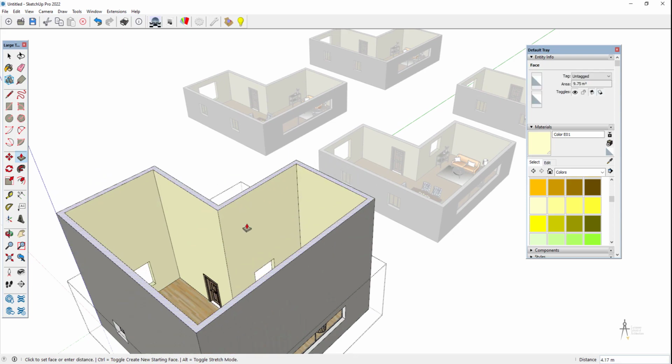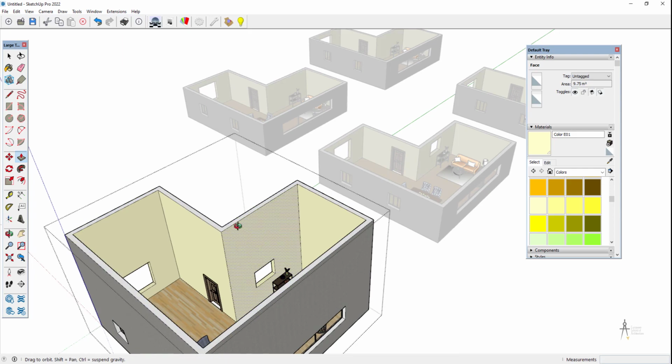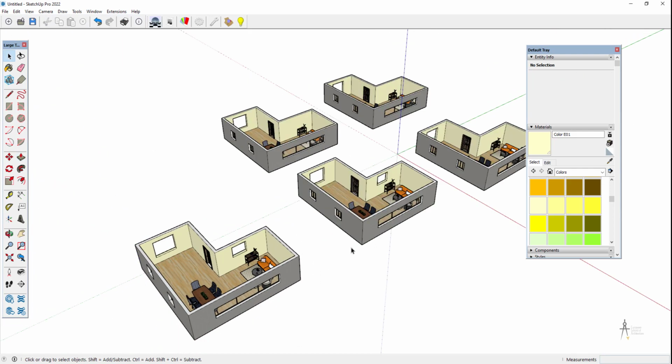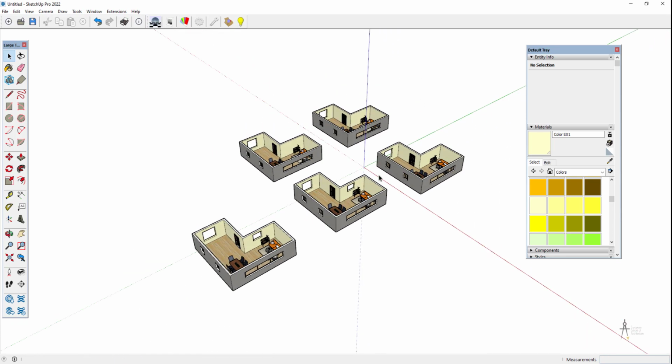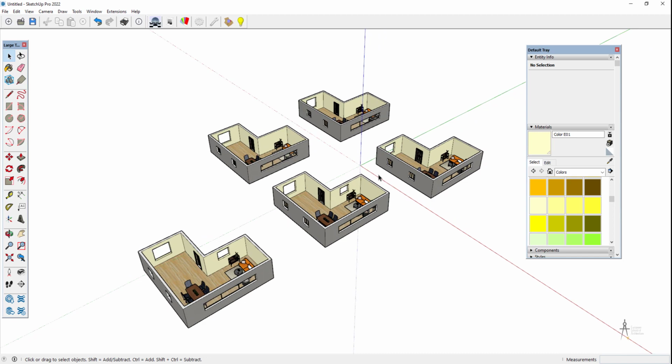I'm going to make this wall taller, okay? It only changes the one I'm changing. So it doesn't behave in the same way as component does. Component is more for repetition and changing, editing within that repetition. Groups are for having together a certain number of objects in order to work more quickly. Like 95% of the times we are going to be using components, as I said before, because in construction we're always going to repeat and change, and normally what we change, we will want what we have copied to change with it, okay?